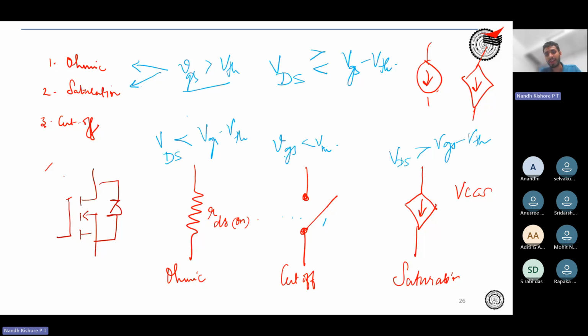A resistor is a passive element wherein the current through the resistor is not dictated by the device. The current through the resistor is dictated by the circuit operating conditions. If you operate as a buck converter, depending on the load, the current is going to vary, and hence the device current will vary. If it is operating as a voltage controlled current source, only then you tell that the channel current, or IDS for practical purposes, is GM times VGS minus V threshold.